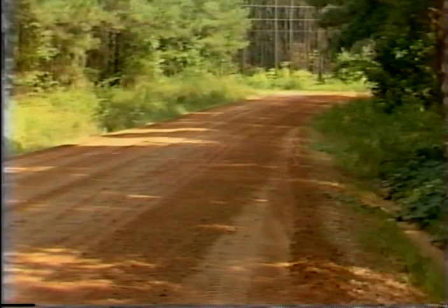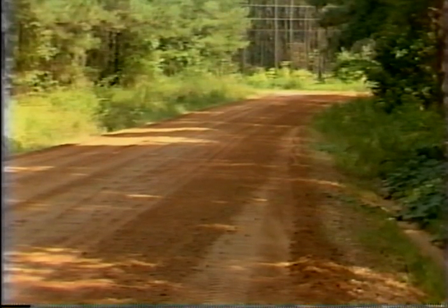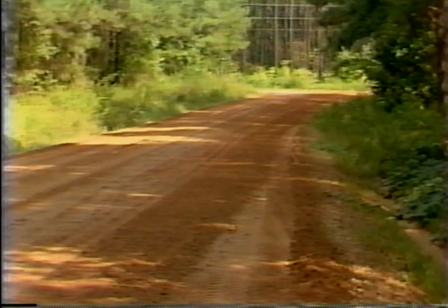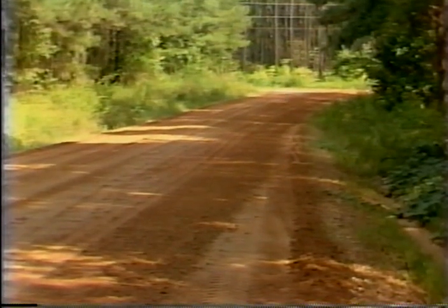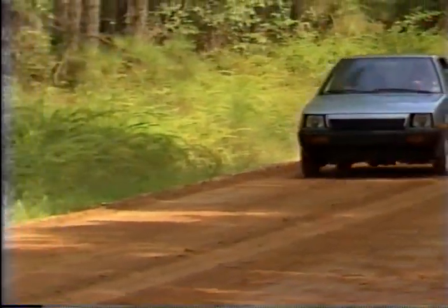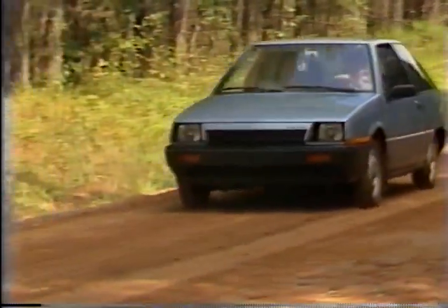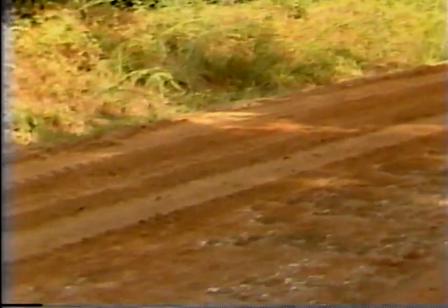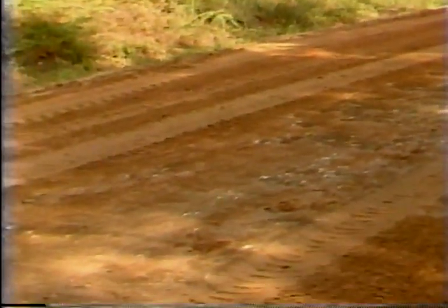The end product is a smooth road with proper crown and shape to allow for drainage. Potholes, ruts, and washboards have been eliminated. The combination of dry weather and compaction under traffic causes a new crust to be formed on the surface of the road.